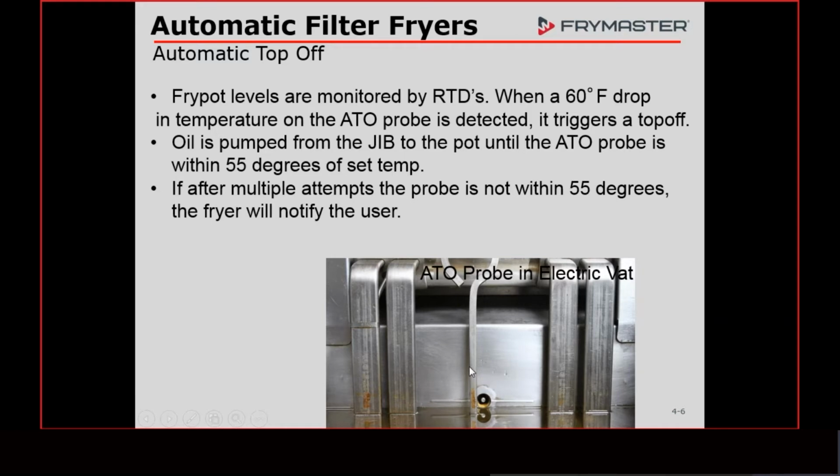Now, it doesn't take oil away, okay, but it will keep it at the right spot. And we tell people, don't add oil in there, because this here is there to do that. Now, when you're filling the pots using bulk oil or whatever, that's a different system. We don't fill the pots completely using ATO, okay, because that would take the whole jug of oil. This is just there to gradually fill the pots up, all right?